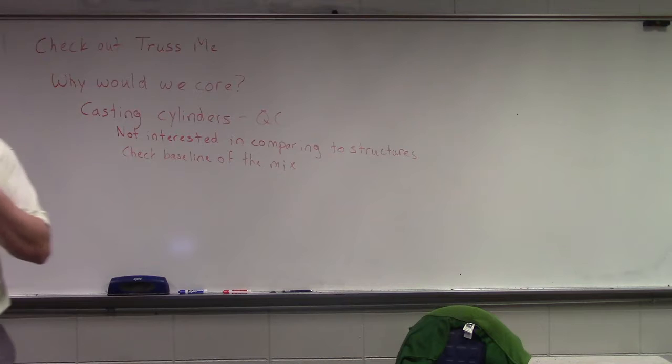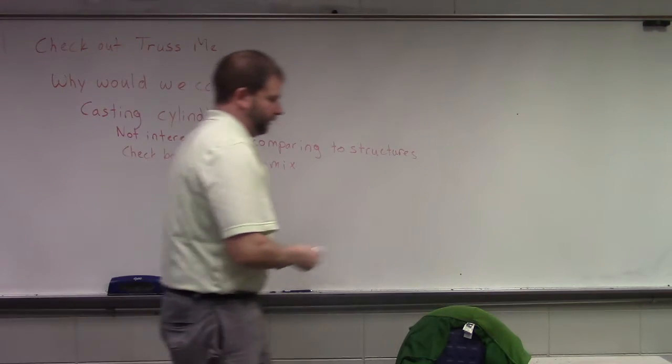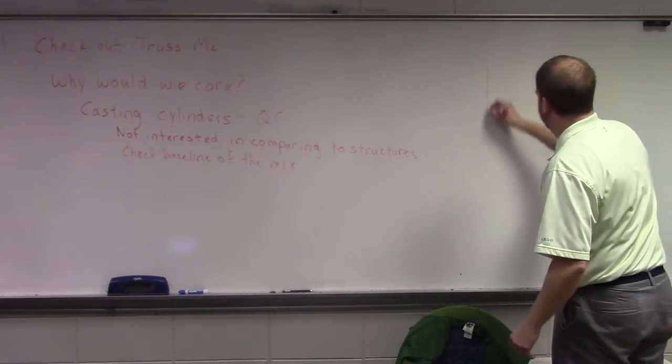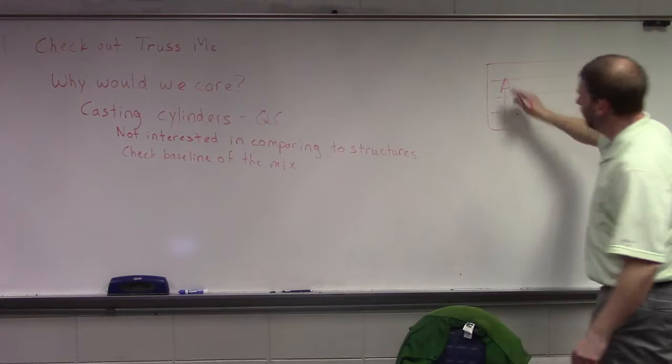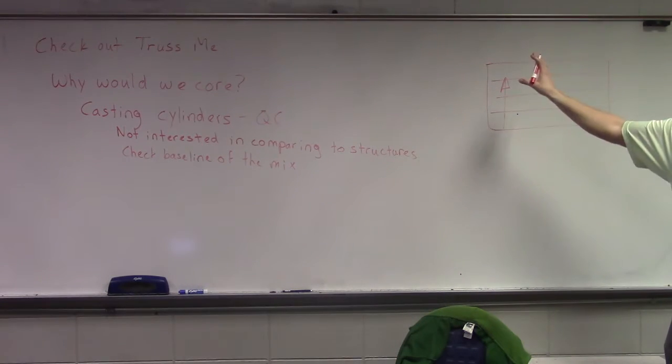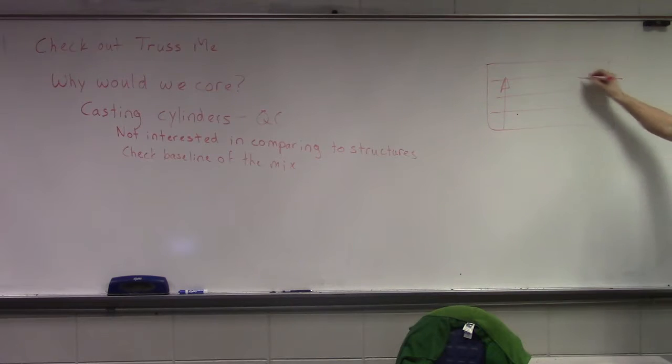This gentleman who was talking about the difficulties with testing high-strength concrete, what they did was a big study where for a bunch of projects they cast these thermal boxes. We're oftentimes interested in modeling what's going on with the concrete, how much it heats up over the time of placement. So they went and cored into these boxes. The problem was the box was cast like this. Okay, so the concrete was filled in this direction. They cored a section out of here.